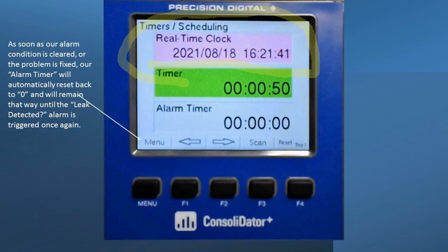I can do that with the scheduler. Let's say I want to turn a pump on every Saturday and Sunday at 3 p.m., but only for 45 seconds, and only if the level is above 10,000 gallons. I can do that with the scheduling. So again, that's just how flexible this device is. The answer to almost all of your questions is yes. I just have to figure out a way to actually do it, to tell the machine to perform that. That was a really great question.